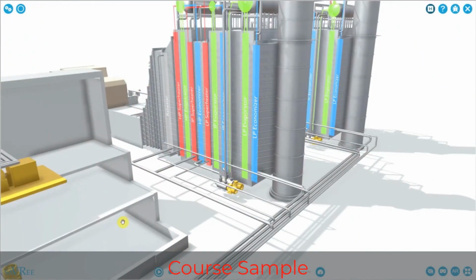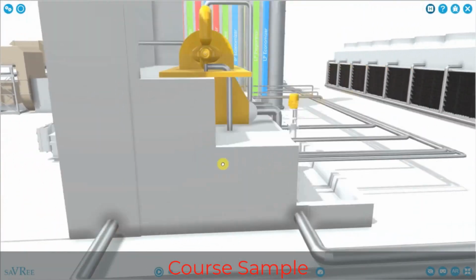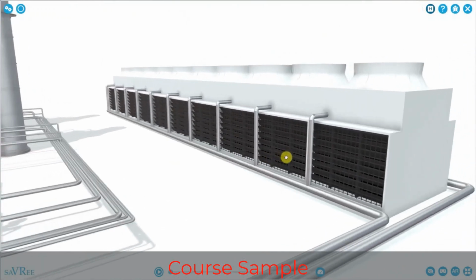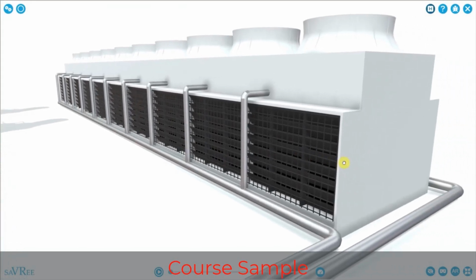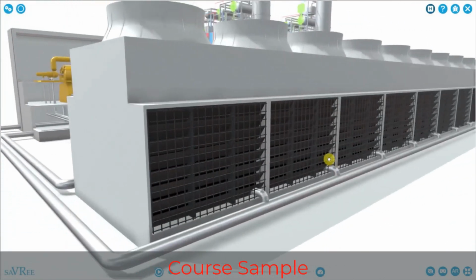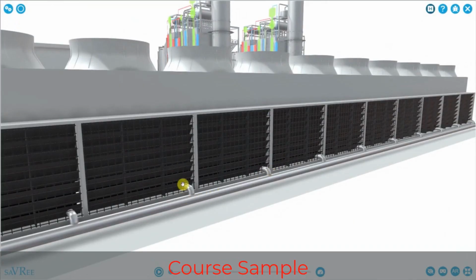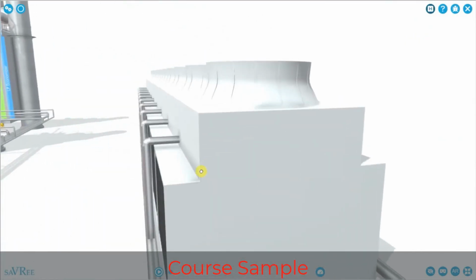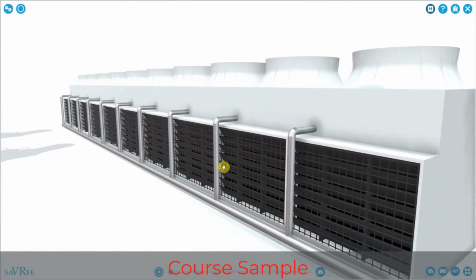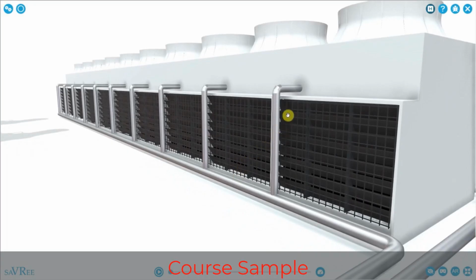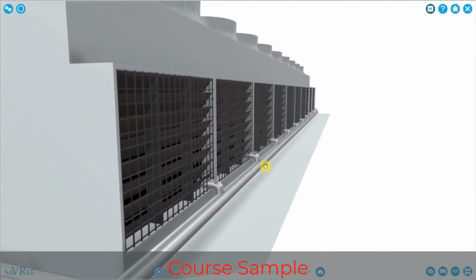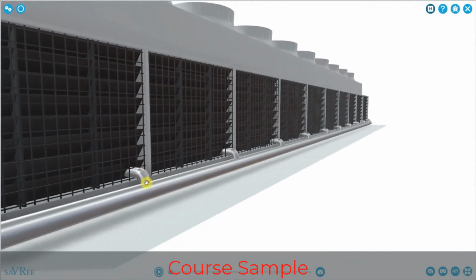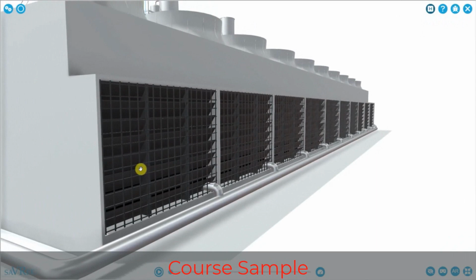How are we cooling the water? We're cooling the water using these cooling cells, also called cooling towers. Now the connections here on this side, if you notice, are at a higher point than the ones on this side. You can see here where my mouse is, there's a connection, and here and here. On the other side they connect at the top of the towers. Cooling water is going to be sent in at the top of the towers, and then it's going to drip down and be drawn out of the tower from the base. The water within our towers cools due to evaporative cooling.